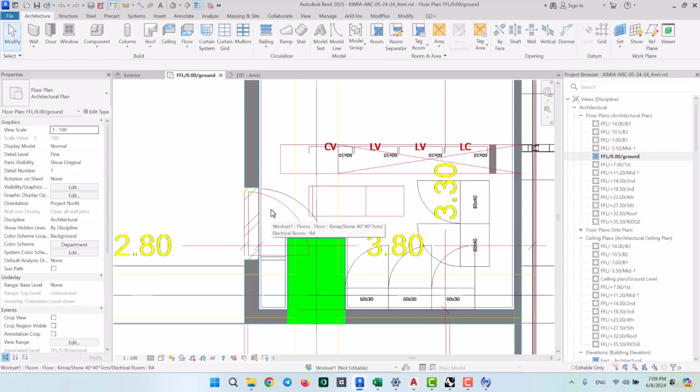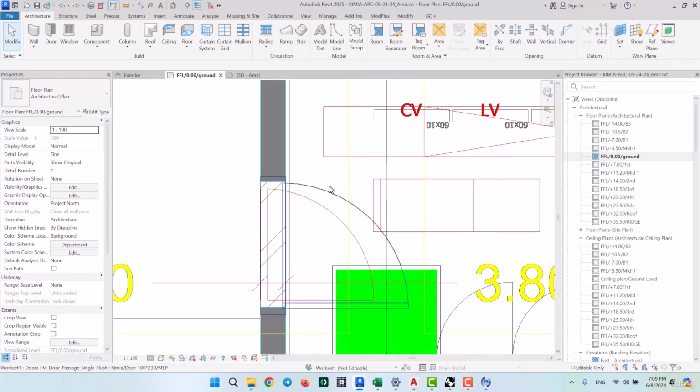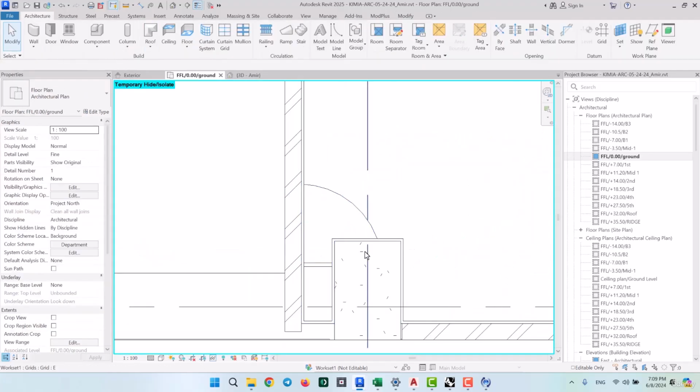Also, a problem that is created by drawing the thin walls from the hard walls separately in projects is that after that we need to join the thins with the hards, and that's because this door over here can't go inside the thin finish wall. So in order to be able to place it correctly, we need to join the hard walls with the finish walls. Now I'm gonna also hide this CAD plan.